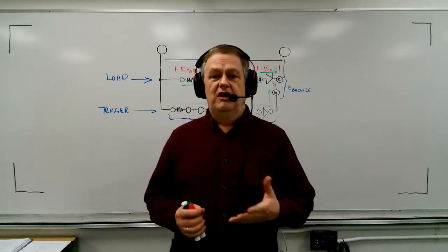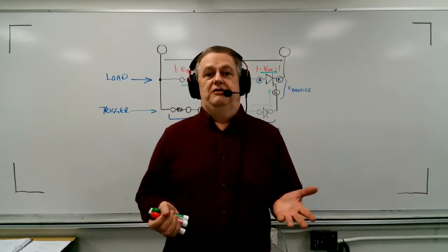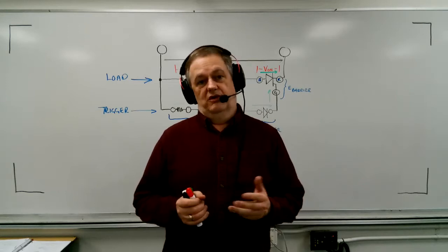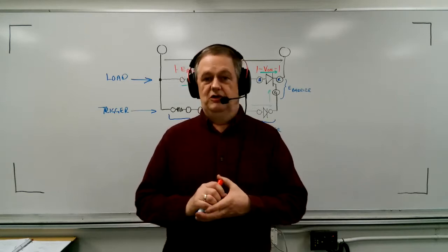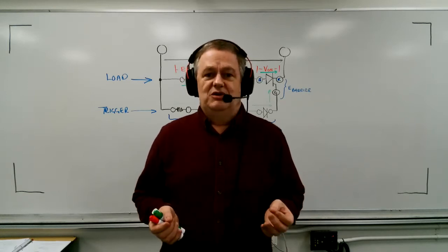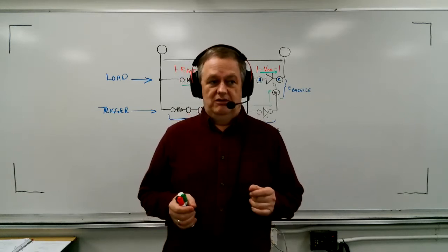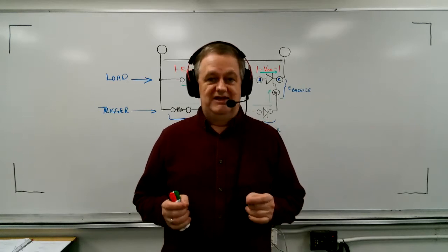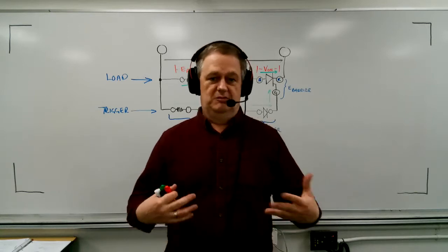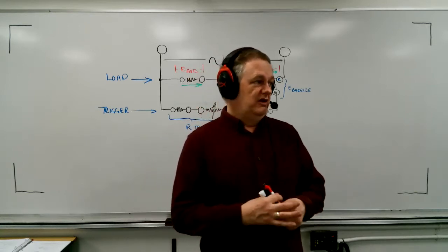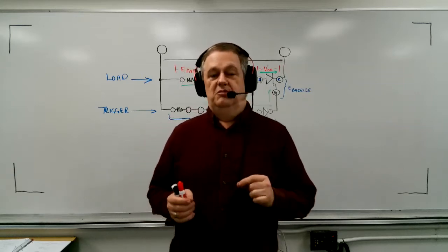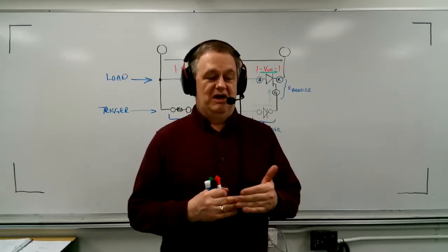But if we're talking about three-phase rectifiers fed from a 600-volt system, or even a half wave fed from a 208/120 system, the diode barrier voltages are going to be really insignificant compared to the line voltage and the total amount of power that we're calculating. So I just want you to be aware of that. Whether or not you count the barrier voltage is really a matter of context.